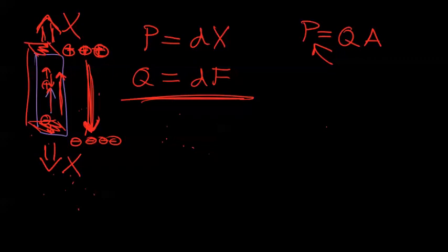Similarly, let's say we have the case where we are applying an electric field to the piezoelectric material, and we put electrodes on the top and bottom. You'll notice this in piezoelectric materials. We have electrodes on the top and bottom of the material. This is the polarization direction. The reason for this is that we can get the entire surface to be at one potential.